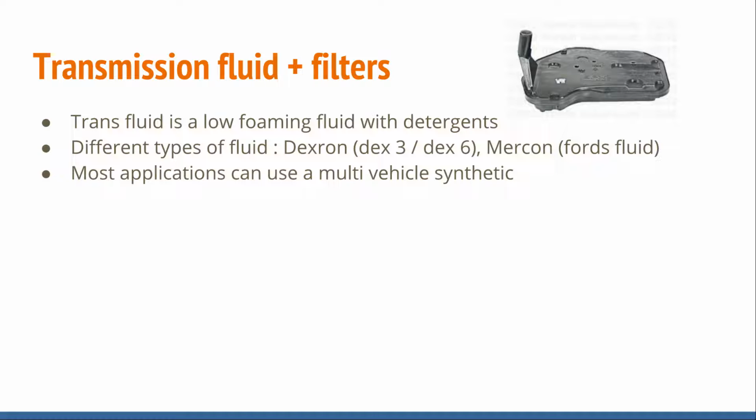So most applications can use a multi-vehicle synthetic. This is what I do in my shop. I buy in bulk and I have a barrel of multi-vehicle synthetic fluid, and I can put that in 80% of the transmissions that come in the door.